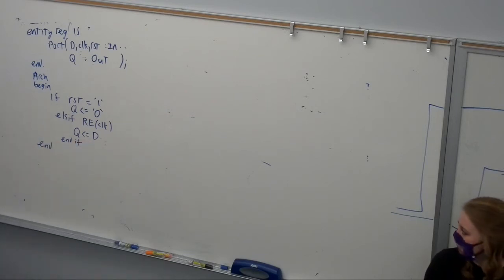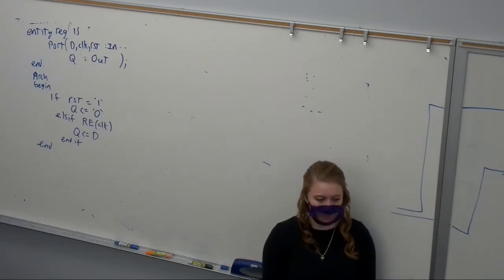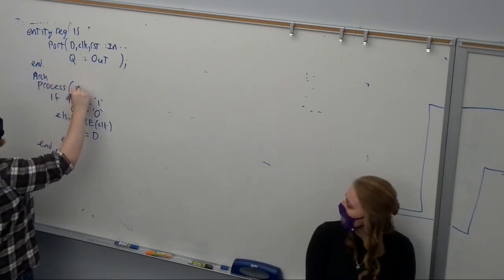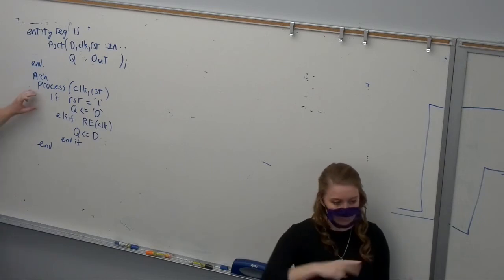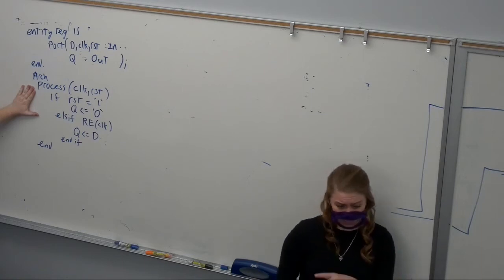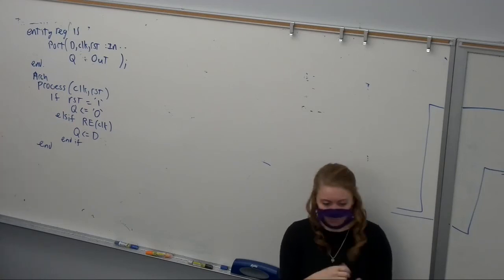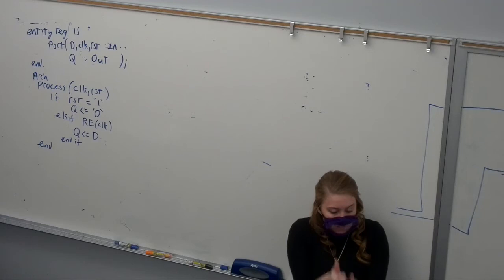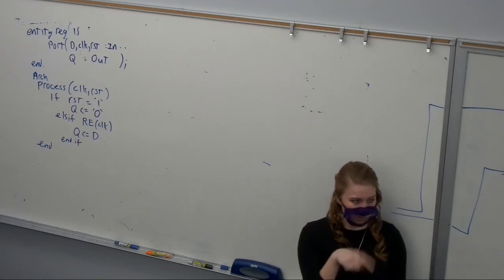Okay, here we go. I've written a D flip-flop. Is this a synchronous or asynchronous reset? Yeah, because it's in the process list, so it can reset whenever, right? Which is it? Asynchronous. And that's because it doesn't have to be synchronized to the clock to happen. Are you guys doing okay on this edge readability? Or are you going crazy? All right.